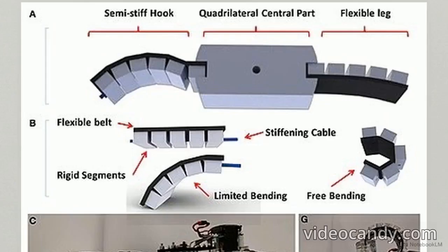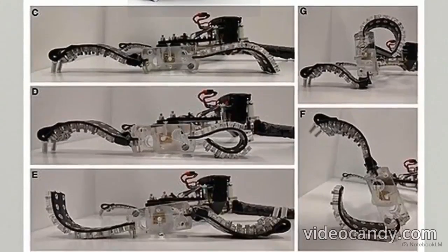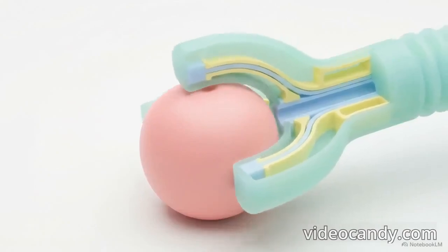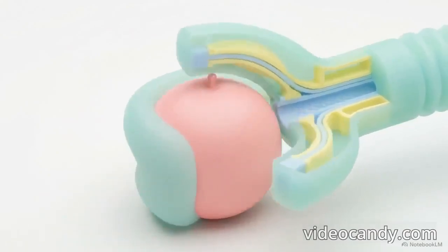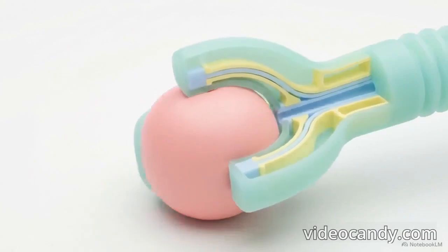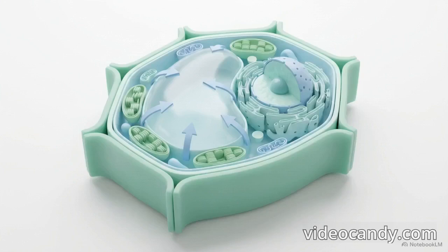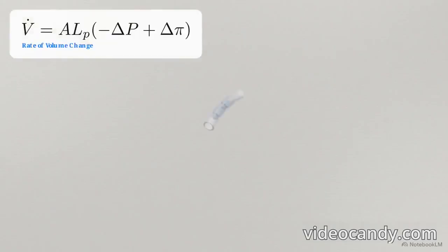Yet, even with advanced mobility and AI, building a robot from rigid metal links remains a severe liability when the machine must safely interact with a delicate marine ecosystem or maneuver inside the human body. This composite breakdown illustrates a radical departure in engineering: soft robotics. This subfield abandons rigid links entirely in favor of highly compliant, flexible materials. Replacing metal and ceramic with soft resins drastically lowers the machine's mechanical impedance. When a soft robot makes contact with a human, the material absorbs the force, making close-quarters interaction inherently safe.